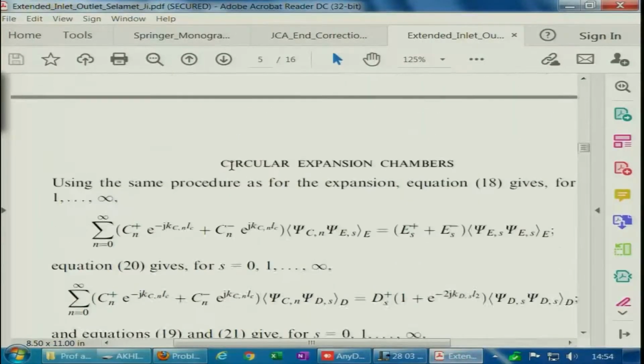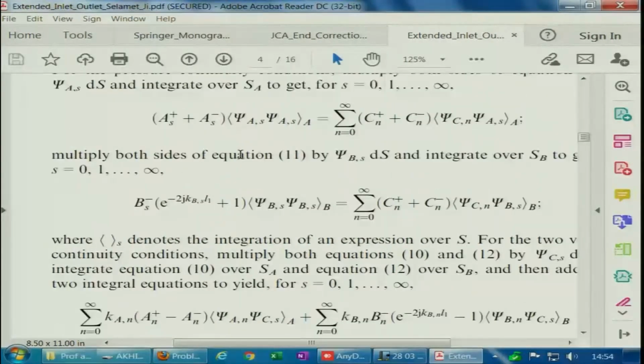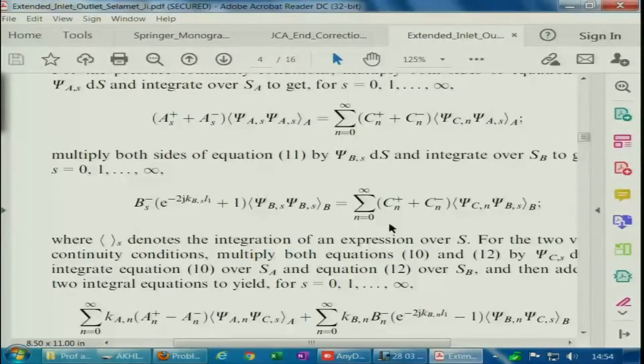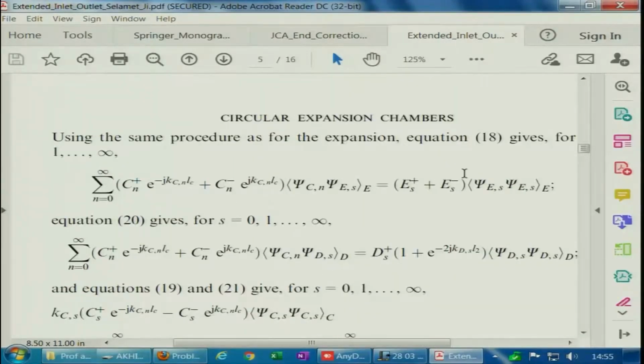What do we do? Now, at the other boundary conditions, there is something that I want you to understand properly. So, here also we have these 3 equations. If we are setting this guy like this, we cannot increase our number of coefficients. You see how many sets of coefficients we have. We have A plus and A minus, reflected waves in the inlet pipe, forward travelling wave and negative travelling wave in the chamber, and B minus. So, 4 sets of coefficients, 1, 2, 3, 4, and similarly we have this set to 0, 5 here and 6, and these two are known.